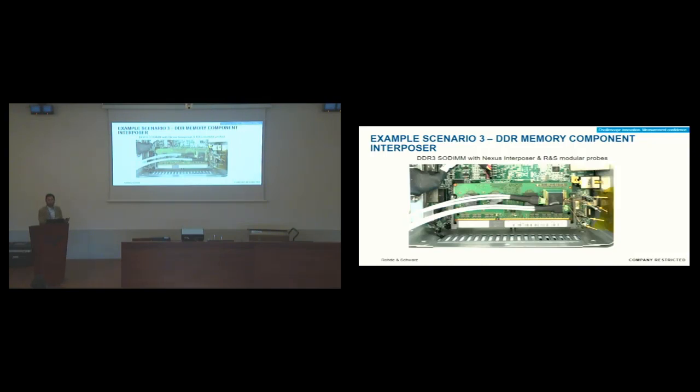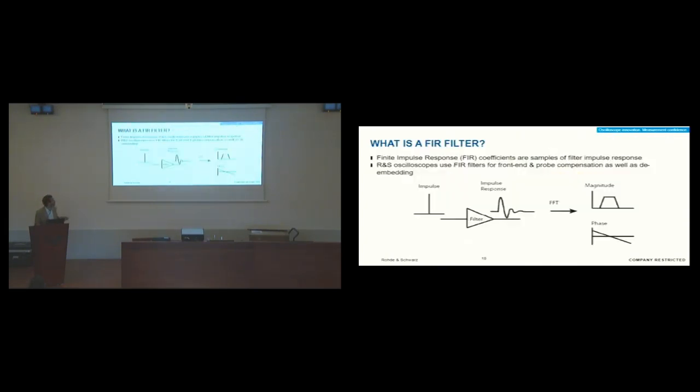Okay, so once we have our S parameters, what do we do with them? How do we use these S parameters to really de-embed? The answer is in the FIR filters. As I told you, a linear time invariant system has a finite impulse response.